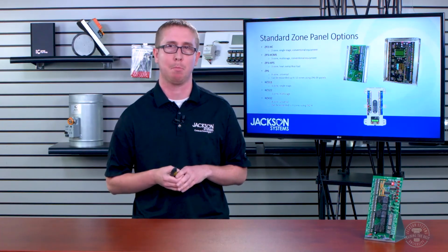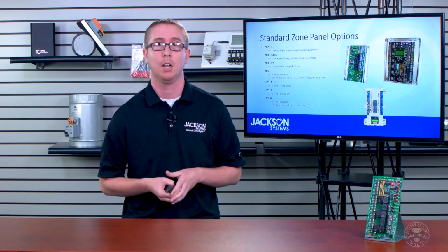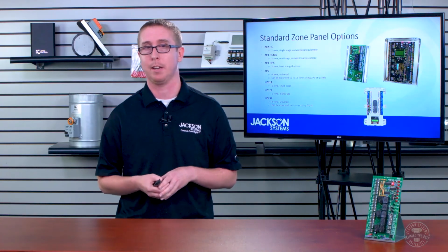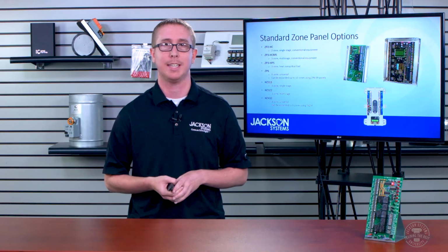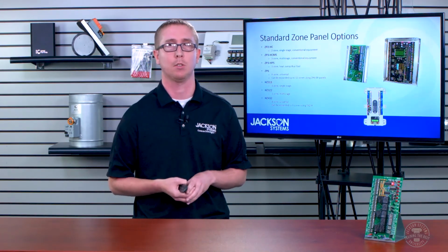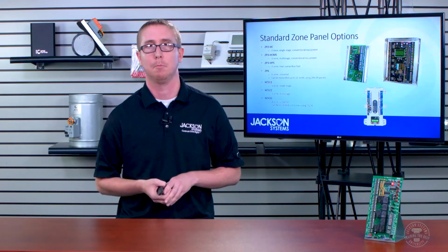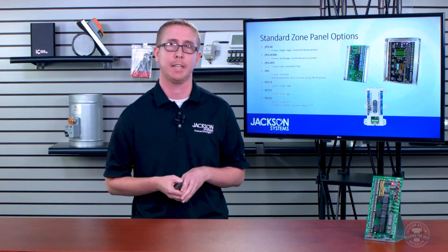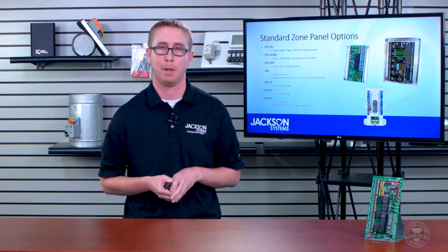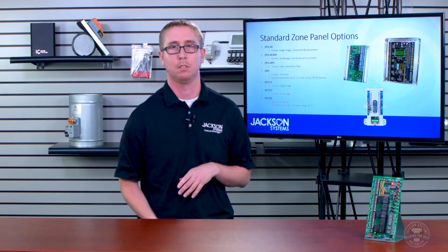panel that can do heat pump or dual fuel systems, but it can only do heat pump or dual fuel systems, no standard equipment there. There's the ZP6, which is a 6-zone universal panel that can be expanded up to 12 zones using expansion panels. From Honeywell, there's the HZ311. That's a single stage 3-zone panel from Honeywell. There's the HZ322, multi-stage 3-zone panel from Honeywell. And there's the HZ432. That is Honeywell's universal 4-zone panel, which can be expanded to 8 using the TAS4 panel.